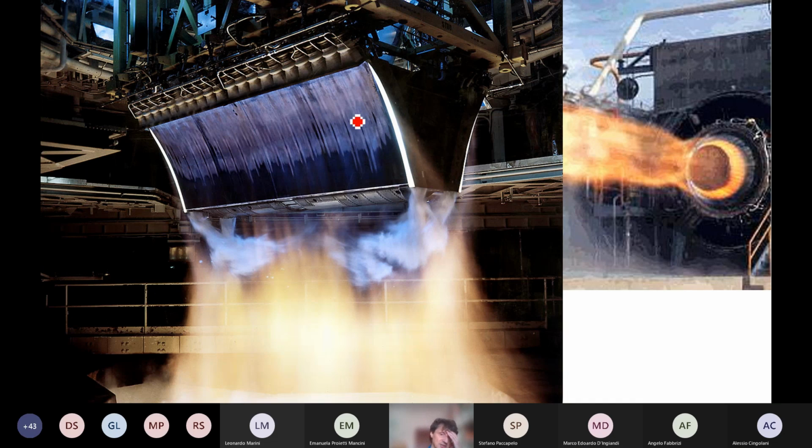These are the couple of pictures of planar or toroidal aerospike nozzle. So with the expansion, external expansion, there is the jet here. You see here there is a conventional nozzle exhausting along this wall that allow you to have different pressure behavior as a function of the altitude on these walls, and so it leads to the side adaptation.